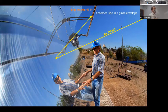So there's another reason we put the absorber in a glass envelope. Daniel? Keep away from the outside air. Yeah, we want to reduce convection heat transfer to the ambient air. So we put it in a glass envelope to lower the external flow convection heat transfer, right? Wind is going to blow over that absorber tube. That's bad. It's going to suck energy away that we worked really hard to put in. So that's why we have it in a glass envelope.